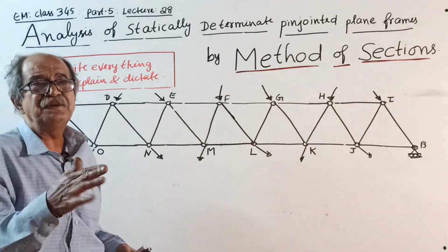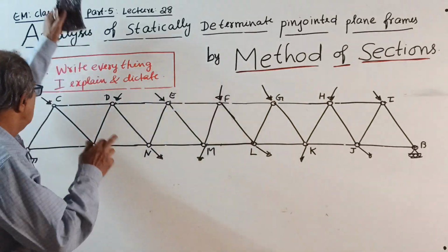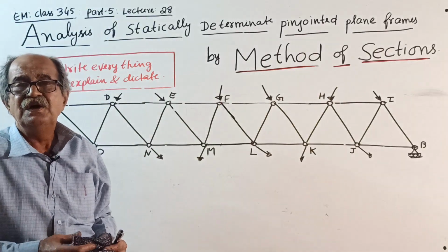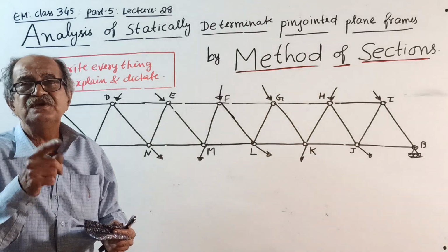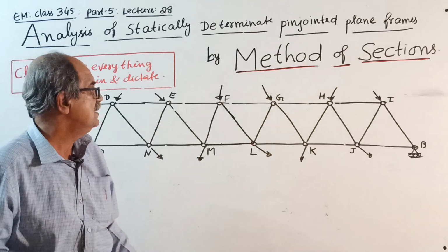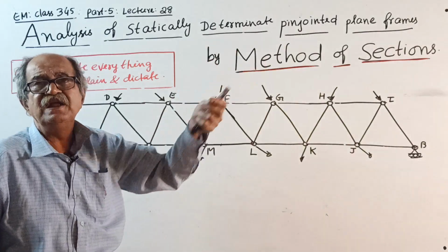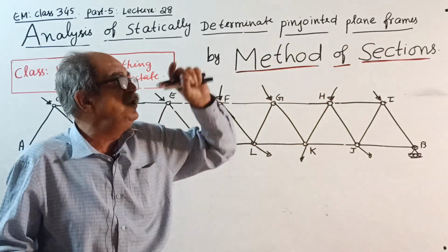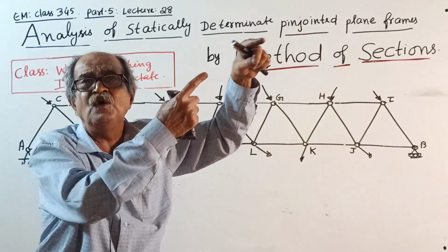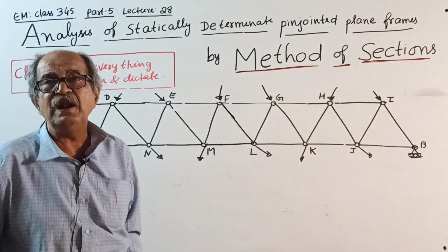We don't consider compression or tension; you change that later. So the number of unknown forces from members to the joint should not be more than 2. That way you solve and get the answer. Then continue joint by joint. Once you solve one joint, when you go to some other joint, the previously solved joint result is known to you. Anyway, so many questions are over.